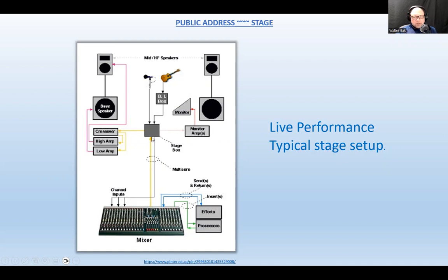The disadvantage of the digital, if you can say that, is if that one cable is damaged, well, you've got to get yourself another cable, because all of those channels are down. They're not coming through. If you have an analog system and one channel goes bad, there's some break in the cable, or maybe a bad connector or something like that, then that channel is out of commission. All the rest of them are okay.